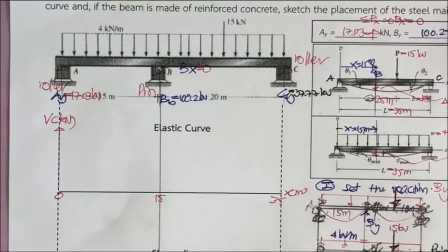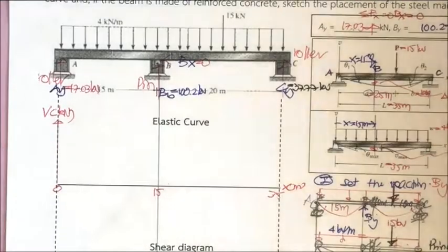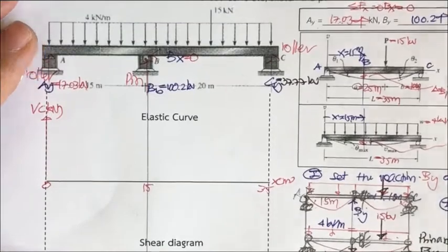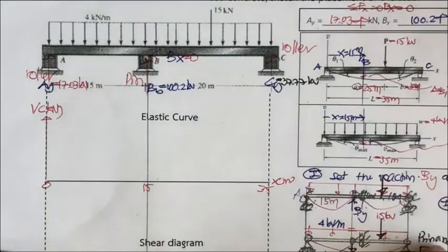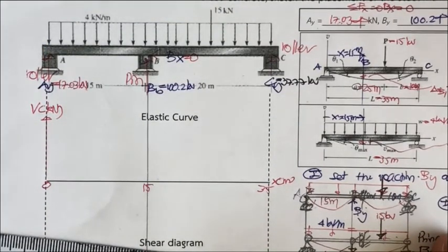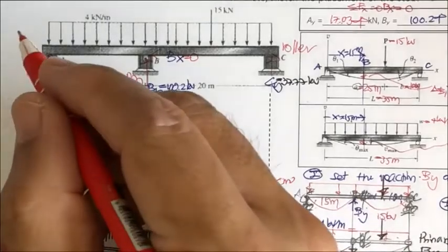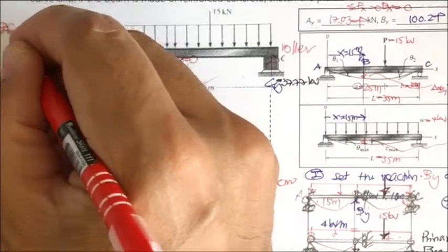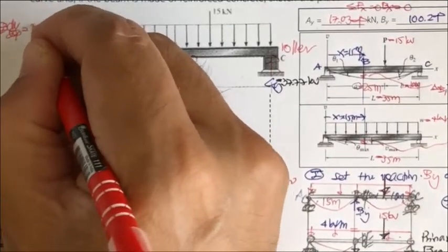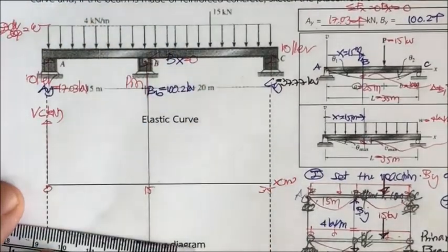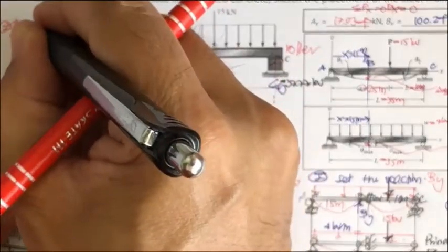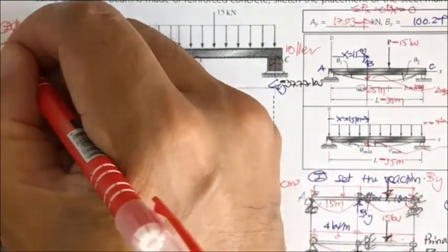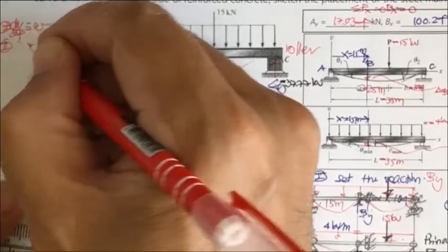And when you do this, you're going to use the graphical method to help you, right? By using the graphical method that you have, you're going to have the first one. You may review that. The first one we have is what? dV by dx equal to w. No, equal to minus w. And then if you do the integration of this, you may have what?